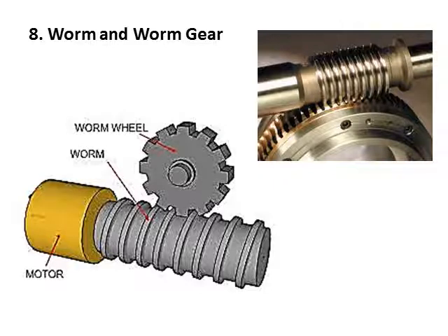Worm and worm gear is a very special kind of gear arrangement. It's very similar to the rack and pinion arrangement, but here the mode of motion is rotation only. One gear is attached to the motor, and you have to transmit power from the first gear, named the worm, to the second gear, which is disc shaped with teeth cut on the outer surface, named the worm wheel.